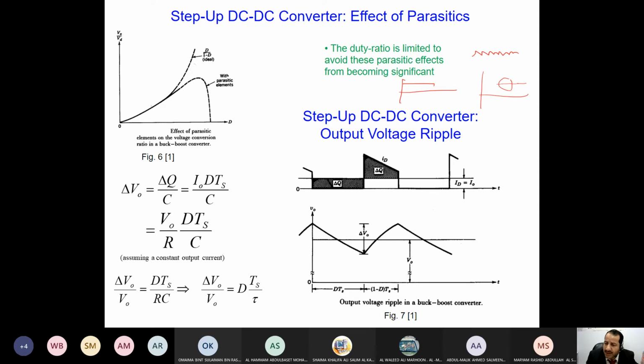But it's written on the nameplate of the device. When you purchase a device, the nameplate tells you the type of converter, the specification, the switching frequency, okay? And so the ripple in voltage. And if you want to design, you need to specify how much ripple you accept for your converter.